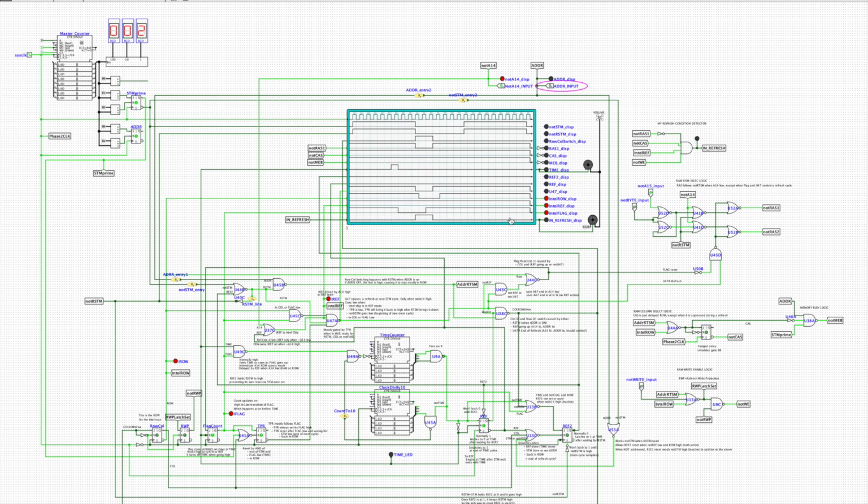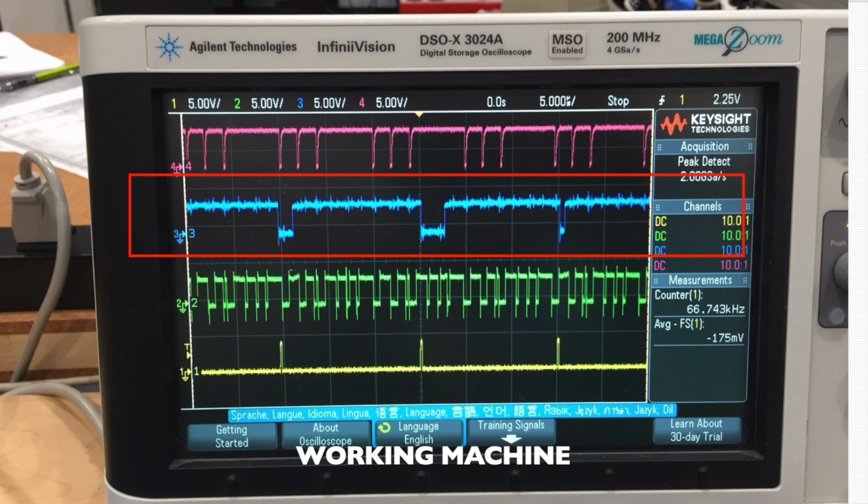So when I realized that those were two completely independent and complicated refresh mechanisms, it started to make sense. So let's wait for the next refresh cycle on this one, and this is a refresh when we're accessing ROM. And let's look at what our counter does. So right now the counter is mostly up. The refresh is going to come up, and there you go. Here comes the refresh. And the counter goes down, and it's going to come back up after the refresh cycle has actually happened. So in this condition, the blue traces that we saw on the scope will be mostly up and sometimes down.